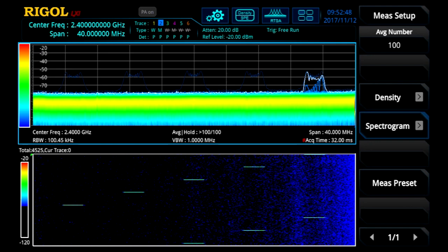The top of the screen is a density plot. This shows many captures of the data together and color codes it for how often the power in that frequency is in that region. Therefore, parts of the trace that are found occasionally, such as these low-duty cycle pulses, appear bluer. Signal levels that are more common would appear warmer, moving up the color bar on the left.